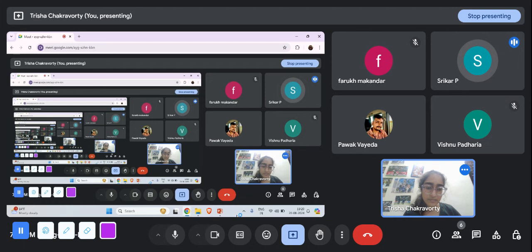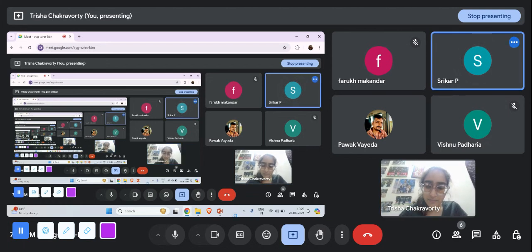Sure, ma'am. And also one more question I do have, particularly when talking about bearing type. While calculating the bearing strength of the bolt, we have the formula kb into thickness of the plate, fy value of the plate, and all. We are considering the properties of the plate, and we are assigning it as the bearing strength of the bolt. How is that justified?